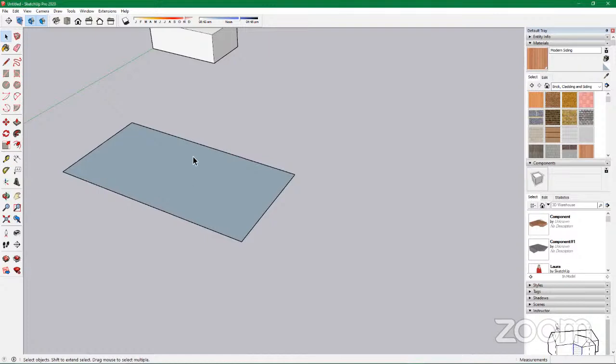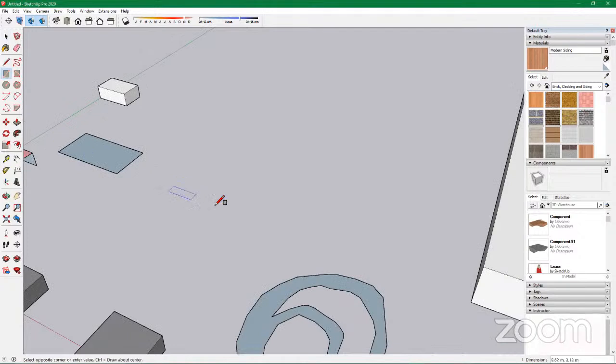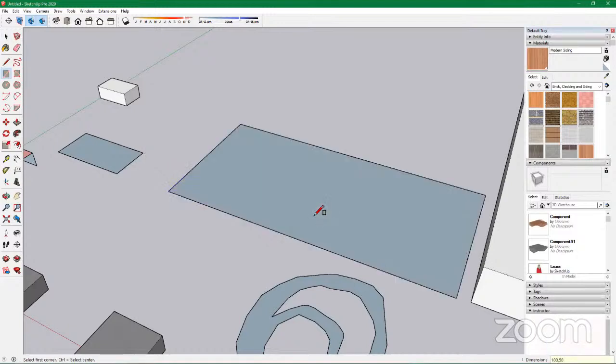So you understand that part, right? Where you have to impute data, even for the rectangle. You click on your first point. Now, looking at it, you will know which part is the larger part and which part is the smaller part. So you see the smaller side there is 14.25 meters, while the larger part there is 52.70 meters. So now you will have to put the first one, which is the larger part, followed by a comma, and then impute the second one. So let's say you want 100 by 50, do 100, 50, and enter it. So you have it like so.